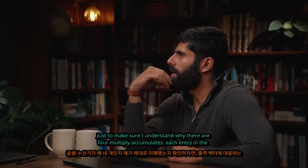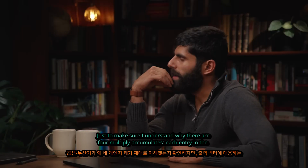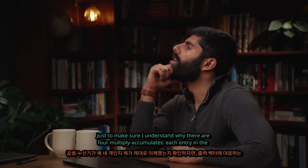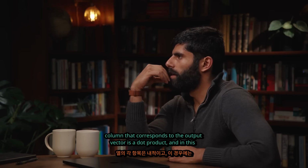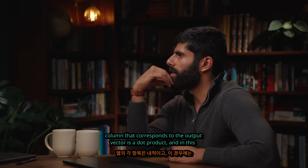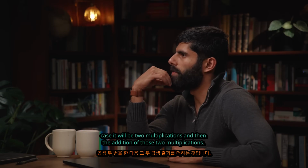Just to make sure I understand why there's 4 multiply accumulates. Each entry in the column that corresponds to the output vector is a dot product, and in this case it'll be 2 multiplications and then the addition of those 2 multiplications.